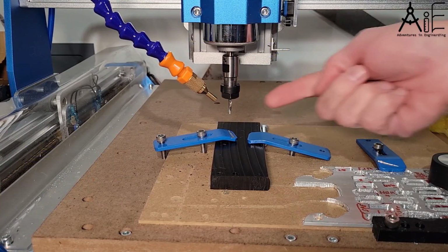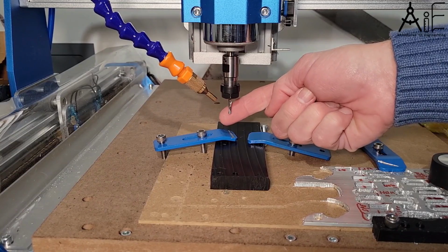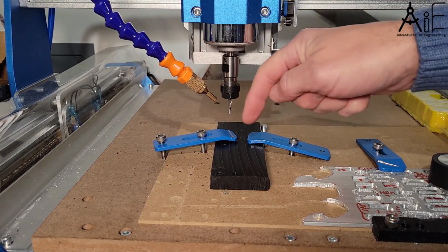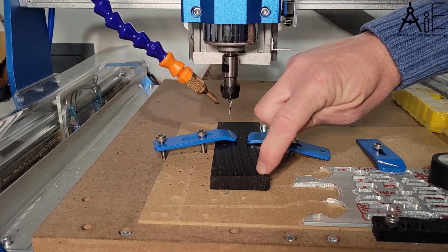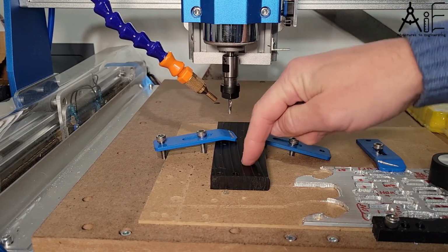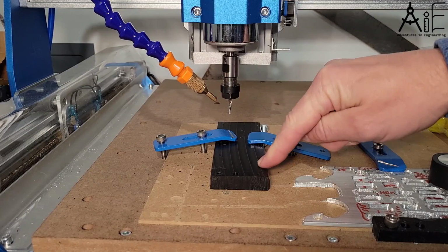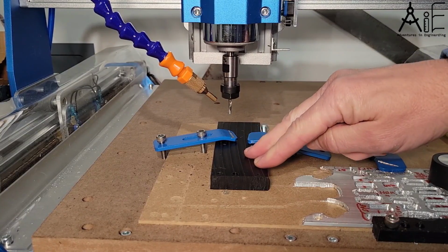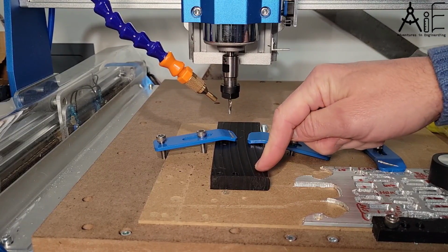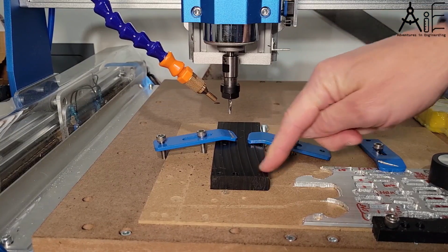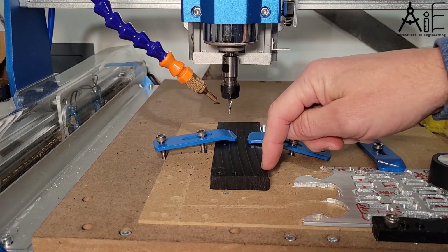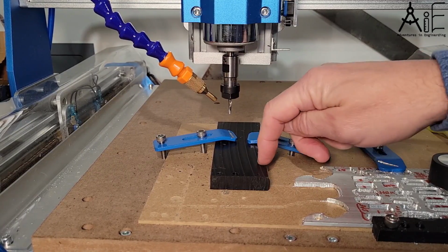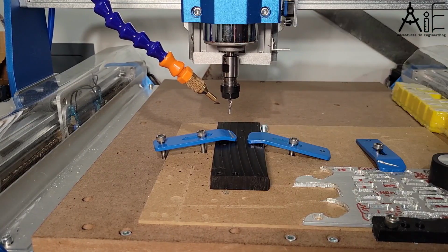All right, I'm starting this process with the 1/8 inch bit, and I'm just going to move it over and zero it at a hole that's already in this piece. This is just a 13.5 millimeter thick piece of plastic, just a leftover scrap, but it allows me to refine the process of making the threads. And then when I go on to a real part, I don't have to worry about ruining it. I've already sorted out my process.